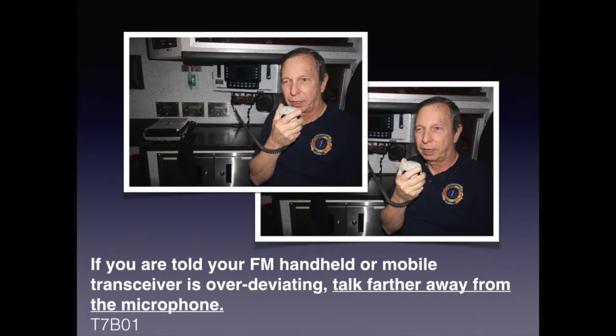One common issue that we encounter all the time is people talking too close to the microphone. So if you're told that your FM handheld or mobile transceiver is over deviating, talk further away from the microphone, please.